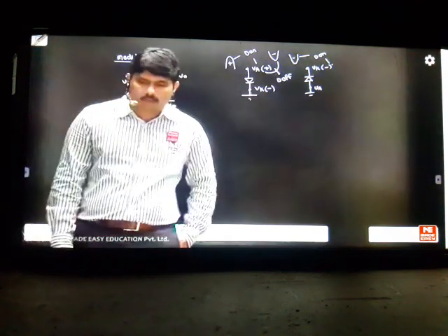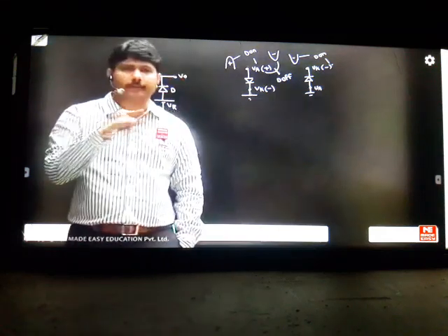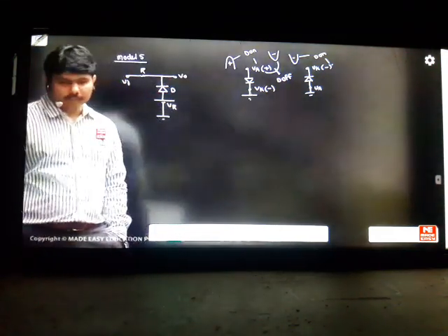Yes, we can say they are working as rectifiers, but only if the reference is 0 volts. If I give a positive reference or negative reference, we cannot say they are rectifiers. A rectifier is nothing but 50% clipping. I think now it is clear.